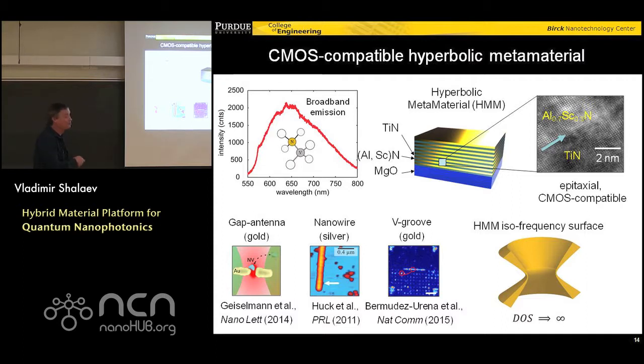It's like one superlattice, one single crystal, made of plasmonic, dielectric, plasmonic, dielectric, plasmonic, dielectric, 20 layers and each 4 nanometers in thickness. It's quite a spectacular result in terms of material science and fabrication. And this material effectively has negative dielectric permittivity in the XY direction and positive in the Z direction.